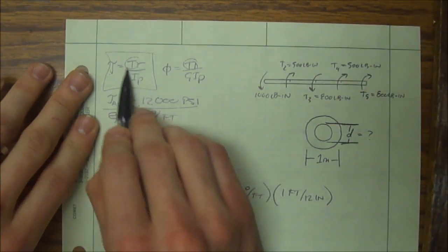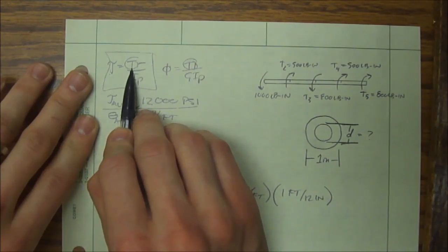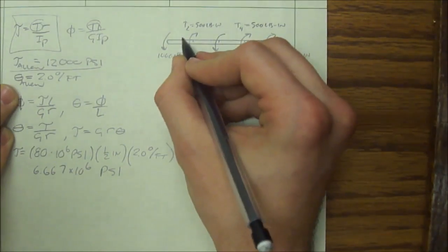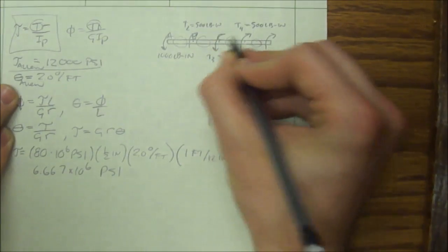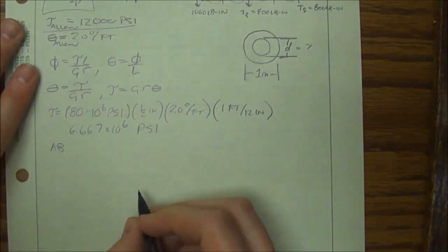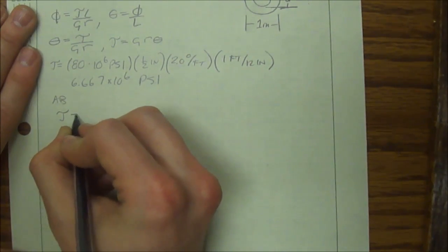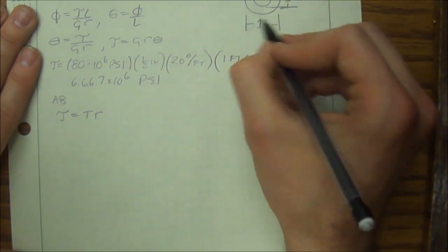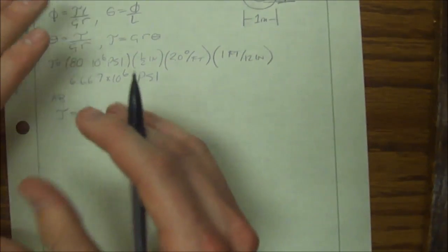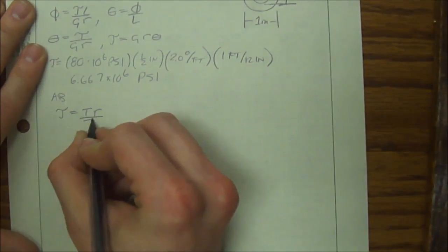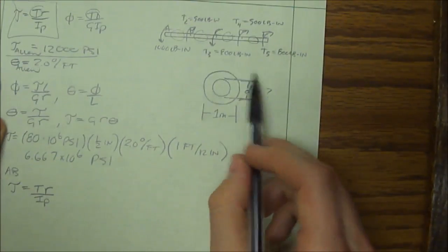And now remember what this torque means. This torque means internal torque. We're going to have 4 different internal torques. We're not looking at the applied torques, we're looking at each segment. If I label these A, B, C, D, E, let me start with AB. So I know tau, I know T, I know R is going to be my outer radius, where we're trying to push it to the limits, the outside of a hollow bar that's going to be failing first. And our IP, that's where our unknown D is going to come into play.